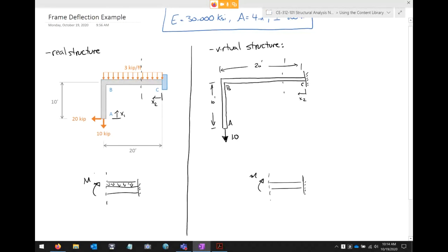The point I'm making is I could very easily flip this and put that down, and there'd be nothing wrong with that as long as I'm consistent and that one goes down as well. And the same thing works for shear, although we don't need shear functions for virtual work right now because we're just integrating little m and big M. So as long as you're consistent, you can do it whichever way you want, because the only thing that matters is what direction you assume. Did that answer your question?